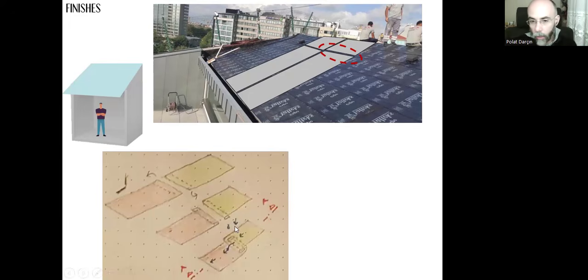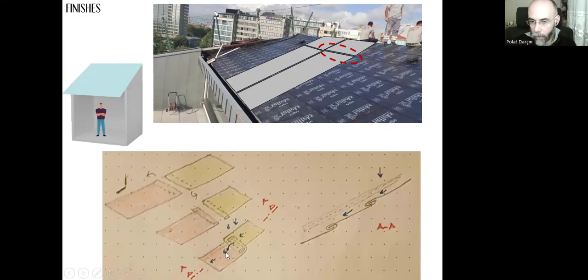And we combine them. The upper one is at the upper level, as you can see, and as the water droplets hit the surface, with the help of gravity, because they are inclined, here you can see the section like this, the water will glide down. There is no risk of water penetrating inside the components of the roof, inside the lower level layers. That's for the horizontal combination.